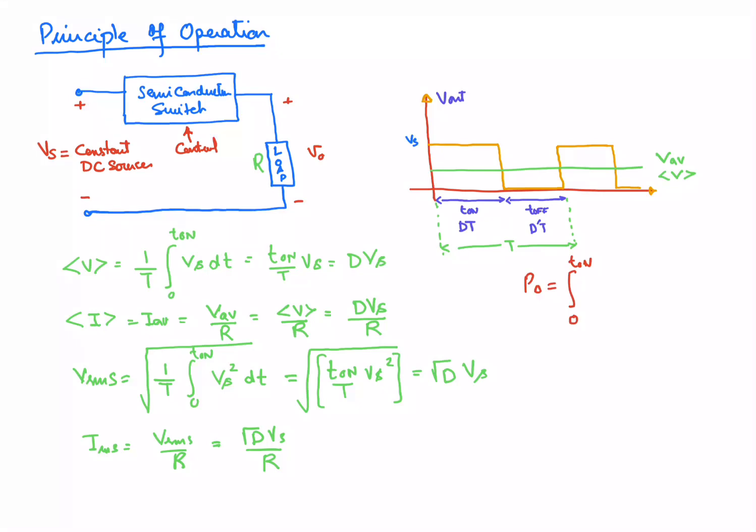So, this is the average output voltage that is delivered to the load that we are going to calculate. So, we are going to find out the area under the product of the Vs and the current at the load, and the load current is Vs by R, right. So, when the switch is in the on state, this voltage Vs is over here and the load resistance is R. So, what will be the load current? I will be equal to simply Vs by R.